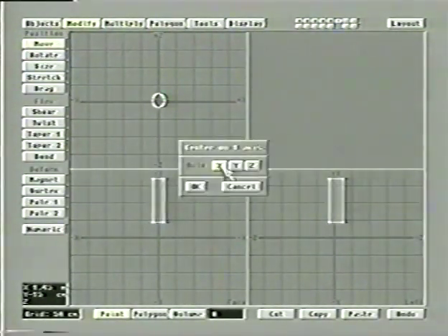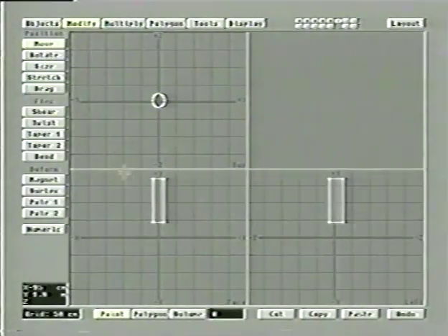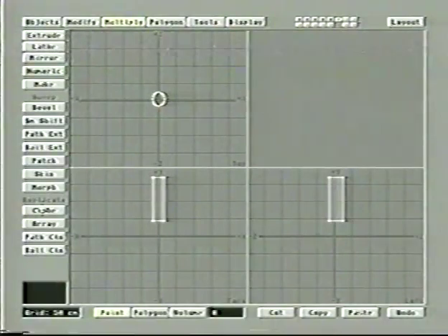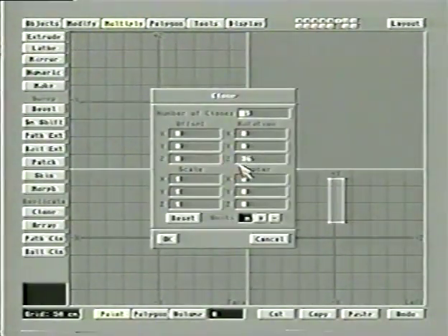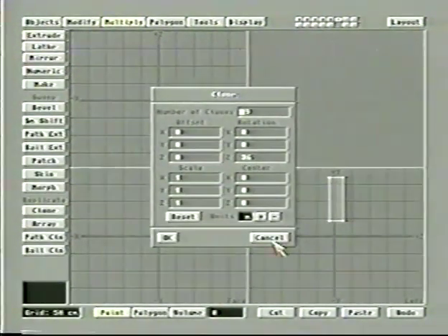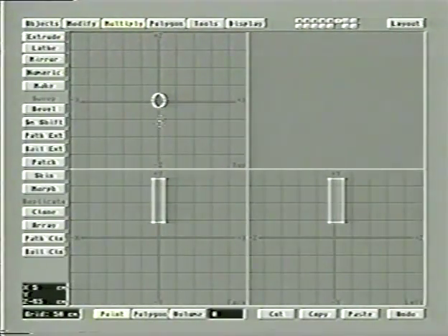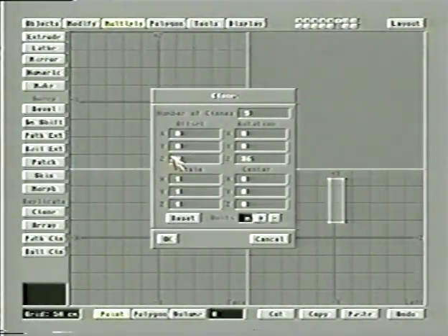and automatically center it on X. Again, using that center 1D macro. Then we're going to go to multiply clone, and I'm going to want it to do 36 degrees of Z rotation, but also I'm going to have it move forward on the Z axis into the negative Z plane. And what I'll do is I'll have each one go 1 meter. So let's just go to clone, Z, -1.